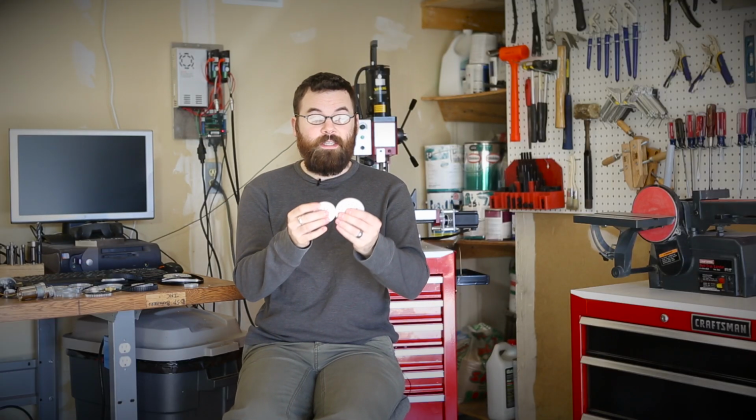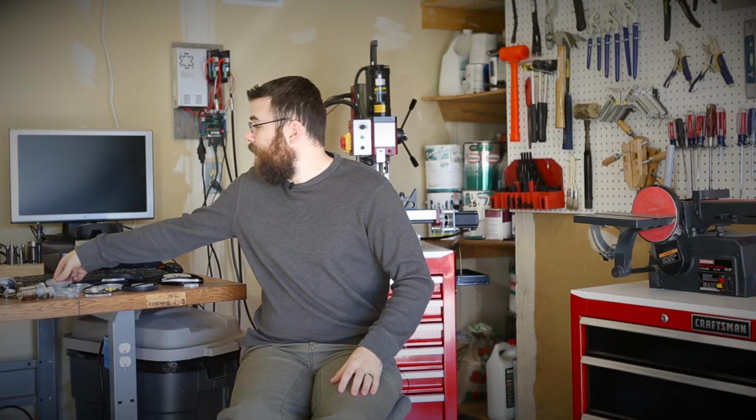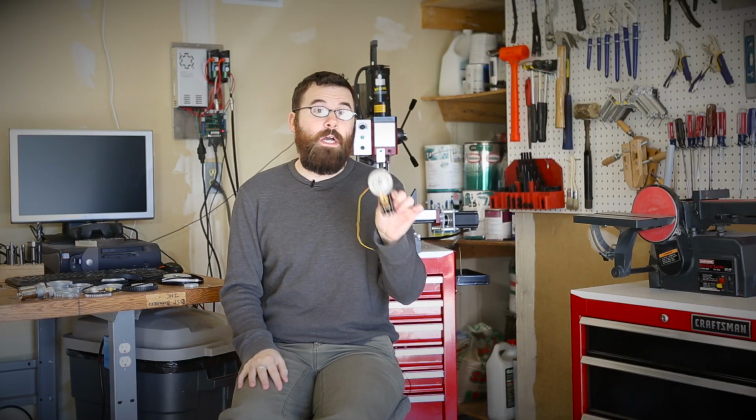Oftentimes when sourcing components for your project, it's difficult to find pieces that all work together. The thing we like about the Actobotics product line is all the gears have the same pitch, the belts have the same belt size, and all the sprockets use the same chain. The other thing that can be kind of problematic about using gears is knowing the spacing between the gears. Because Actobotics uses a standard spacing, you know that the gears are all going to line up. They also have a lot of products like the channel gearbox, where the gear mating is already done for you and you can just select the gear ratio that you want.